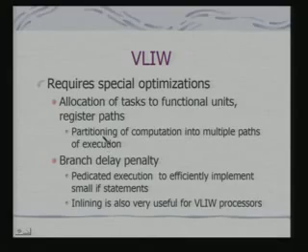So, these dependencies have to be figured out. You have to apply operations to minimize or eliminate the dependencies, then identify the different execution paths and map them on the registers and the functional units, so that the potential of the processor can be completely exploited. In fact, related to this is what is called branch delay penalty.